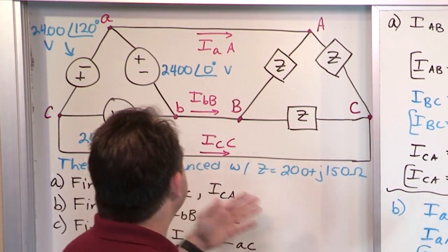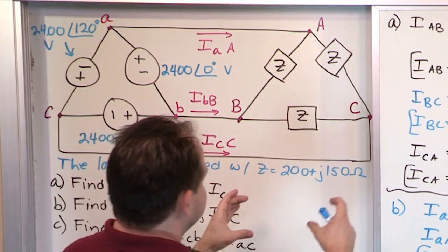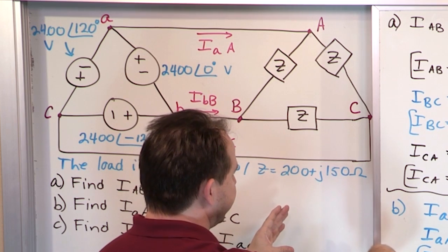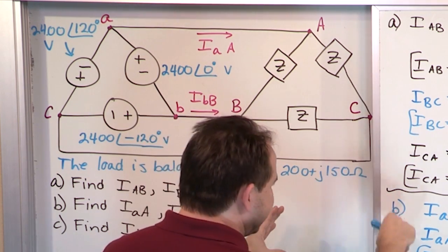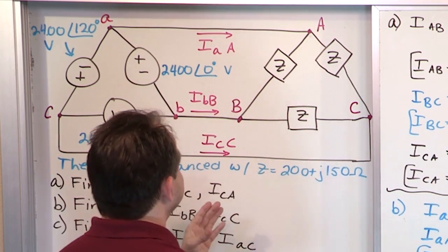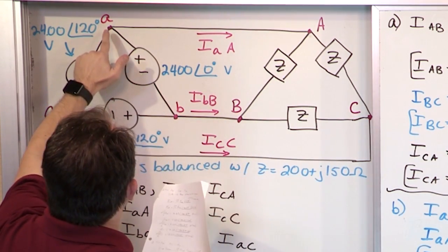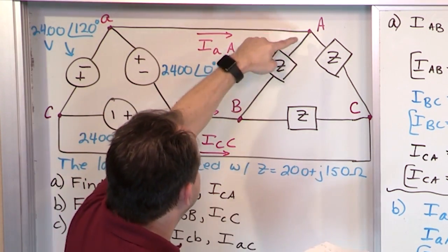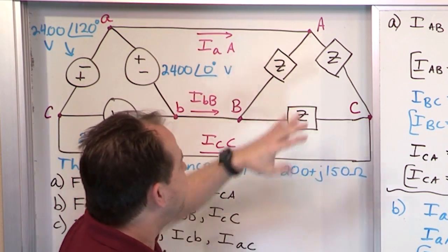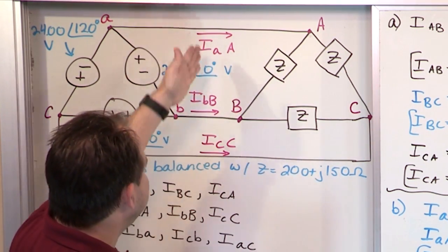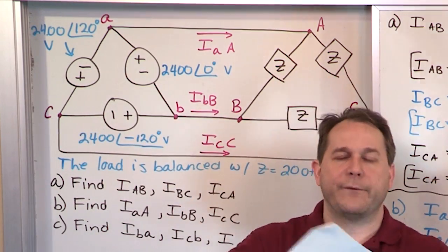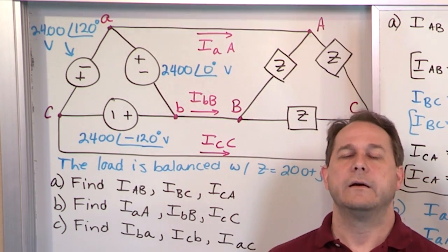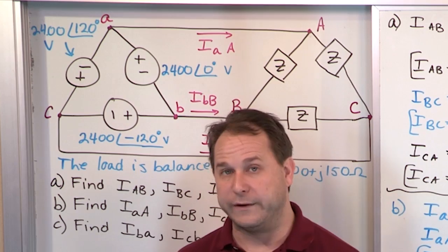It's the case because this is the equivalent circuit of just having a battery connected to a resistor. You're going to have some current coming out of the battery. It's going to go over, and that's going to be the same current going through the resistor. And the voltage drop across that battery is going to be the same as the voltage drop across that resistor because they're physically connected to one another. If you just look at the A phase, the current's coming out of here, however it splits, it goes through the line current. And since everything's symmetrical, this current's going to match this current in magnitude and in phase just because of the symmetry. When you put in a real line impedance, then you have a voltage drop across there, and it can change the phase and it can change the magnitude as well. So it's a good check on what's going on here, but it's important to know that that's not always going to be the case.